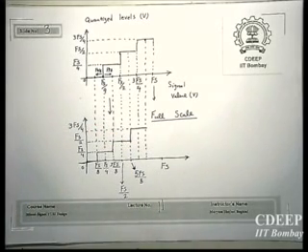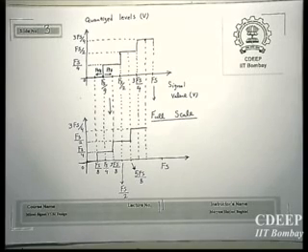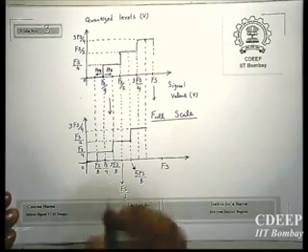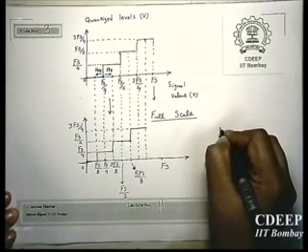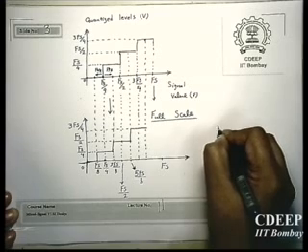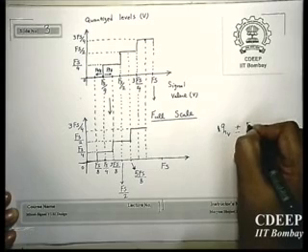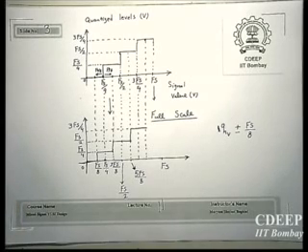Because in textbooks you may see either one of these two, I'm just explaining the difference between them. The second one is better. As I said, the reason is that your quantization level is in between. It means that you will have plus or minus full scale by 8 variation in the amplitude for every quantization level.